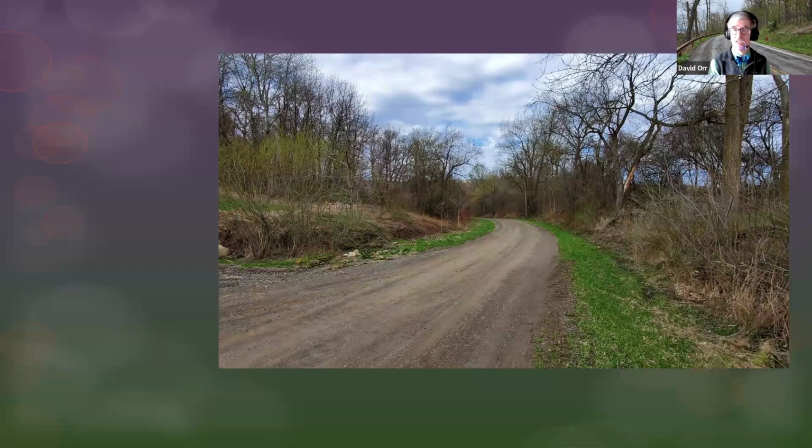So on a gravel road, we're going to have to sign things. And yes, there are some gravel roads I know that are over 1,000 vehicles a day. Yes, they're probably local roads, but you may want to think about signing, again, all of your curves, especially the sharp ones. Okay? So how do we do this?